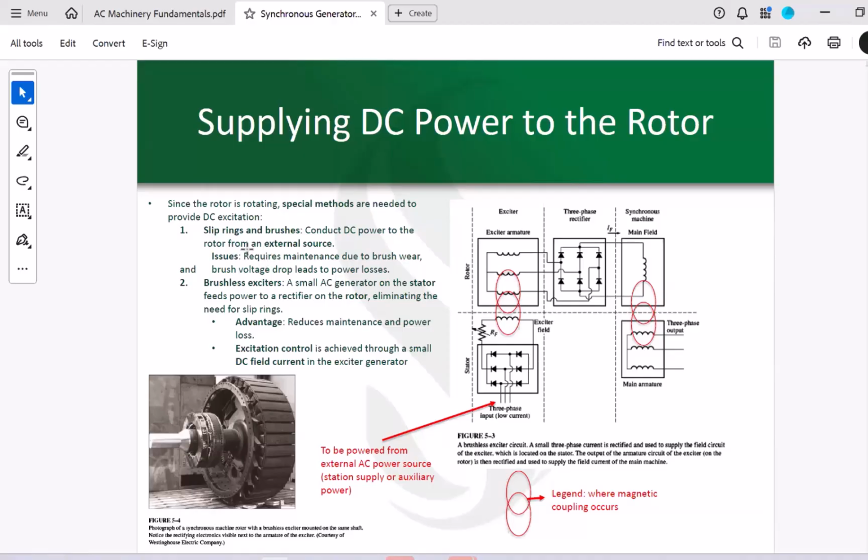in the DC machines. If you recall, in the DC machines, we had fixed and rotating parts, and the rotating parts, through the commutation scheme, would go through the brushes and commutators. Their interaction would be in a way that they could provide a kind of constant current in a generator action, for example. So the same concept is used here in the older machines, slip rings and brushes, to connect that external DC current source to the rotor.